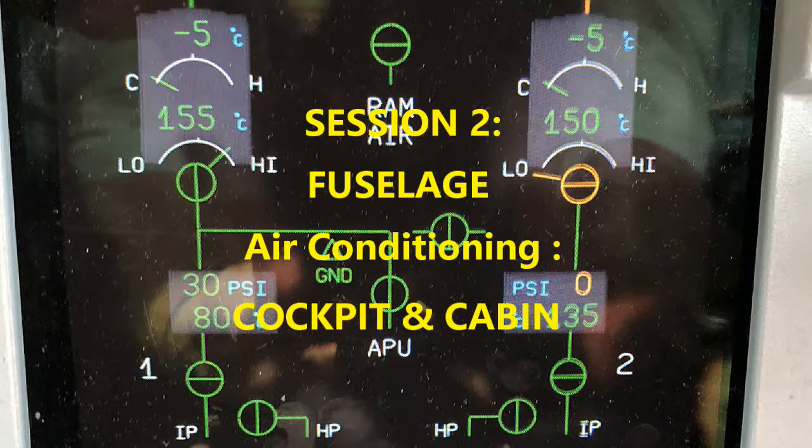All right, you have cabin recirculation fans. The fans are installed with the recirculation ducts. They're powered by a 3-phase 6-pole induction motor that drives a fan wheel. Just so you can have it in your back pocket, the fans operate continuously at roughly 7,700 RPM, assuming obviously you have power.